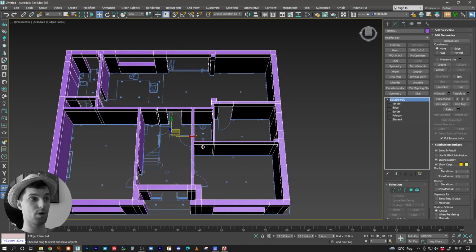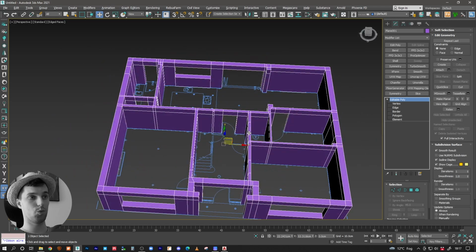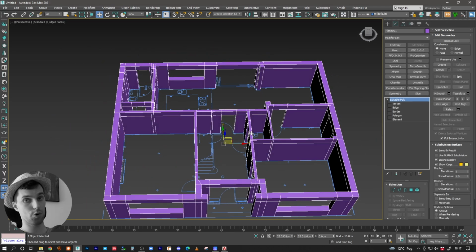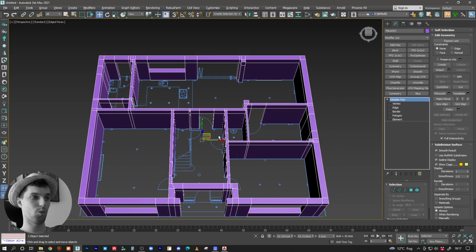And honestly, I remember I was working one time in one of the London companies, and we were building skyscrapers, literally floor on top of floor on top of floor, right? So we had like 50-60 floors. What we actually did is we cleaned the CAD so well and connected all the vertices and splines. So when we imported into Max, we welded everything together and we extruded the walls from the CAD itself, because the CADs were quite good, I'm not going to lie. So that is how we sped up that thing.